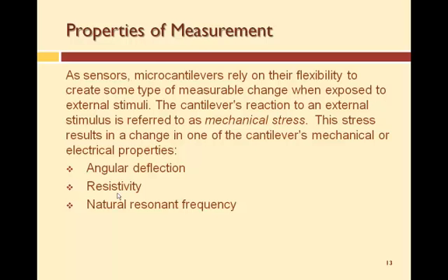So now I have an electrical method of measuring the stress in the cantilever. If my probe coating absorbs a material and it bends, it's going to change the resistance in the embedded piezo-resistive material, and you can detect whether or not it's bending or under stress. It's another way of measuring what's going on.